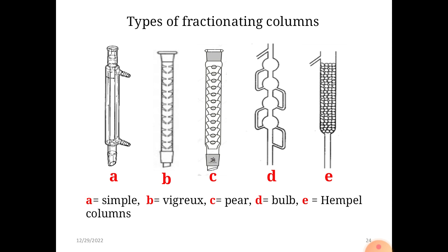The material used for packing should be of uniform size, symmetrical shape, and have a unit diameter less than 1/8 that of the column. It should also be capable of uniform reproducible packing. As the size of the packing is reduced, hold up in the column and rectification efficiency increase sharply.